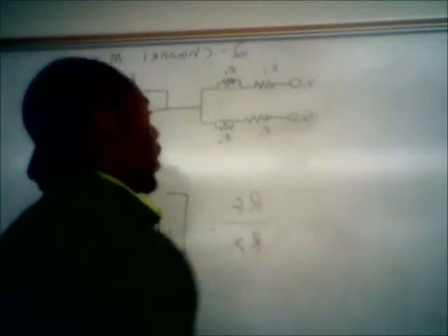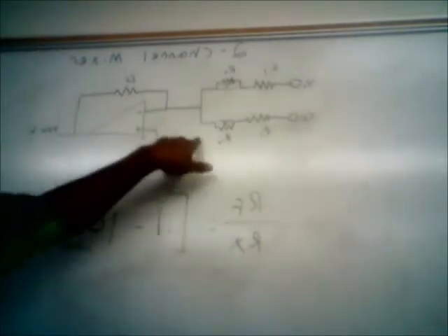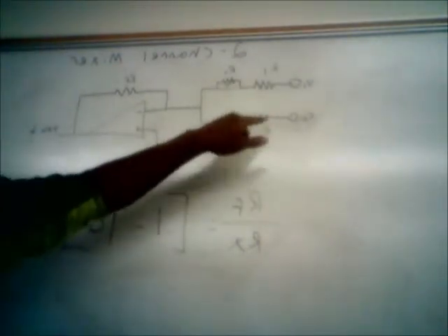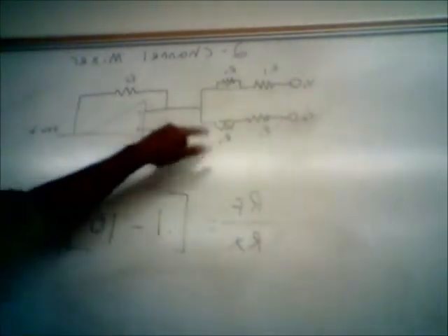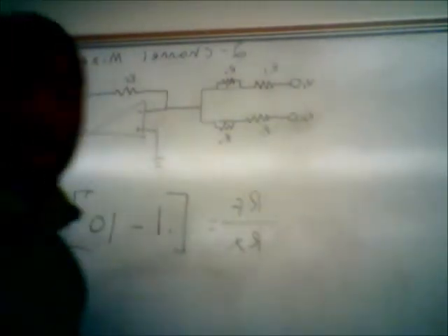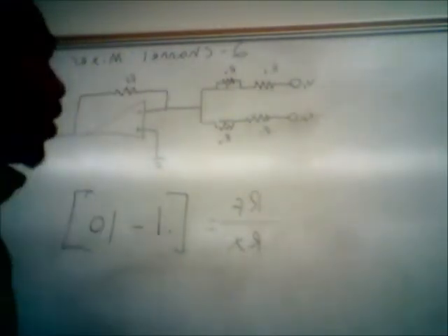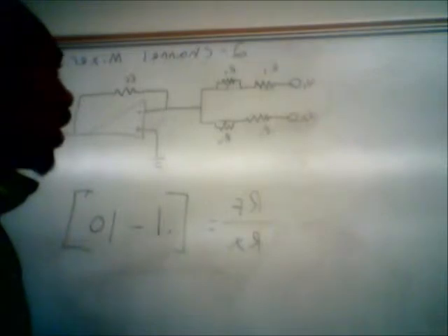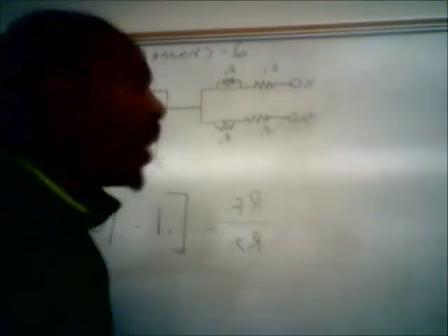Incidentally, you always want a resistor in with your potentiometer, because if you were to turn this all the way down to 0 and there was no resistor here, you'd have the full current coming across this resistor, which is just bad because it's not quite zero resistance, and that's a lot of heat to be dissipating. So it's just good practice to have a resistor there anyway.